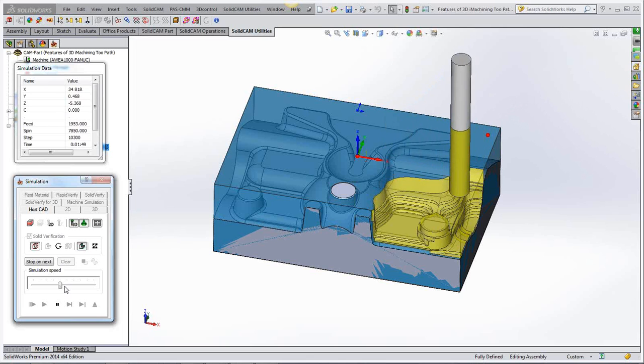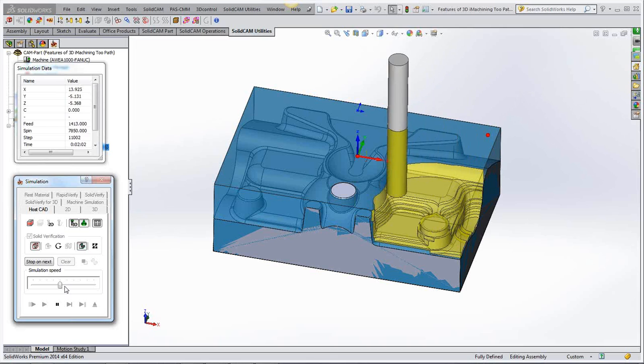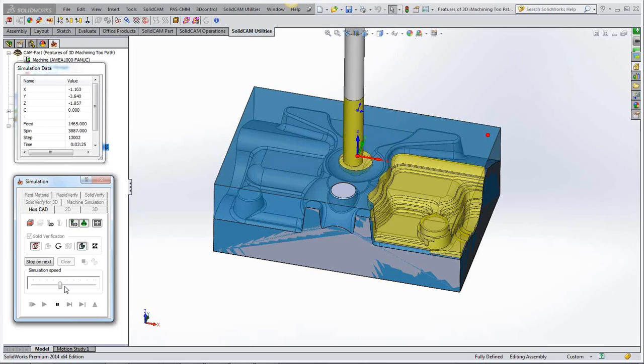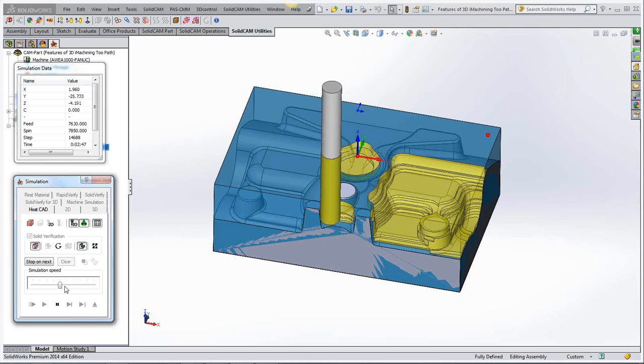As it gets closer to the shape of the mold, it's doing its step ups now, and it works that all out by itself based on the information that you've given it regarding your scallops, etc. So it's finishing that bit off, getting right into the corners there, getting closer to form, and once it's finished that area, it'll pick on another area. It's going to get rid of that little pocket there that's inside that little area there. It's finished with that now. It's going to attack a little area over here that it needs to clear, and then it'll move on to the next area.